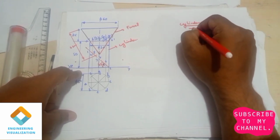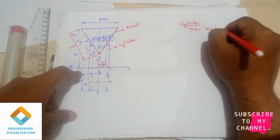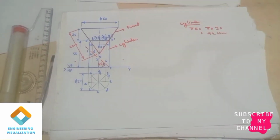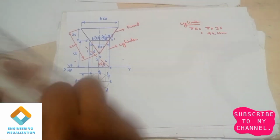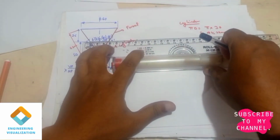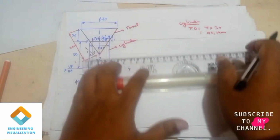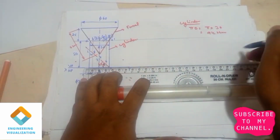For the cylinder we have the formula pi d, pi into diameter. Diameter here is 30. The diameter of the cylinder is 30, so the length we get is 94.24. This cylinder will be done using the parallel method. So I'll be using two parallel lines here, from this end and also from this end.